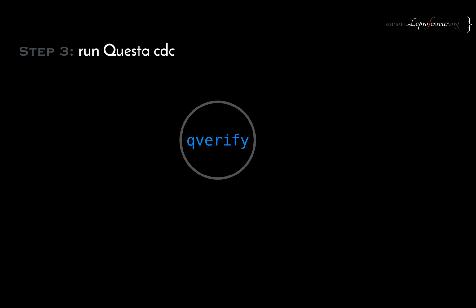And then simply the final step would be to run the Questa tool. qverify is the command. Very good. What it needs: your work directory, which has your design information after vlog compilation, and then your preferences file, the cdc.do file. It will go with the qverify, and then it will generate the cdc.db database. Remember that you can always change the names and whatnot.